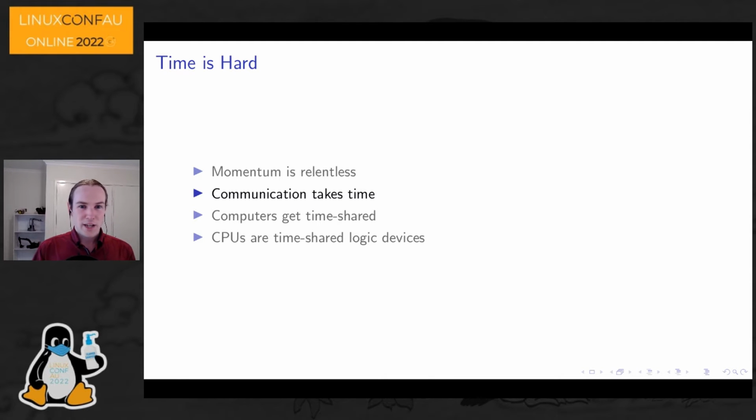Until about 2010, PCs came with parallel ports, and parallel ports could interrupt the CPU. In a CNC machine, you could measure the length of a cutting tool by lowering it onto a conductive pad and stopping when you complete an electrical circuit through it. It was very simple to write software that could use the parallel port to detect tool contact, stop all the motors within tens of microseconds.